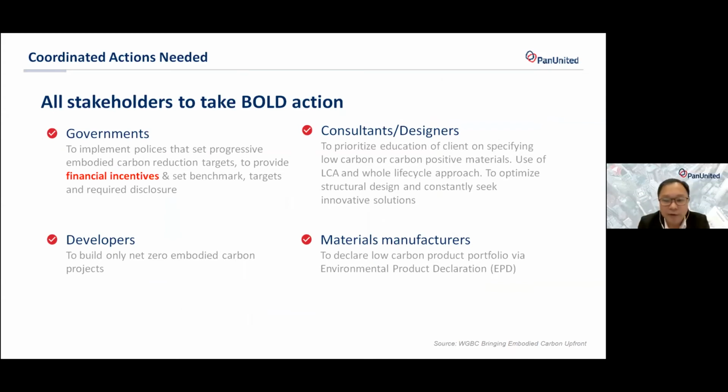And just like I mentioned, from developers, to consultants, or even manufacturers, they have to get ready their low carbon solutions, which I believe the ready-mix companies in Hong Kong are already doing by having GGBFS or even fly ash in their product offering. So the next thing that we really need to change our mindset on is how can we actually spec this low carbon concrete in our products or even in our tender specification.